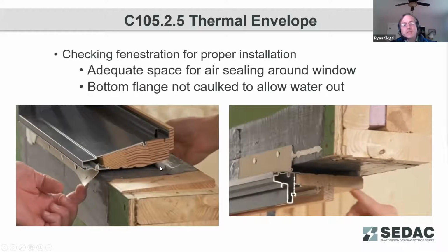And then towards the rear of that, we see there is a bead along with caulking. So we have some backer rod with some caulking to provide that air seal. So being aware that for fenestration, we have at least two different needs. We need to control bulk water and we need to control air.